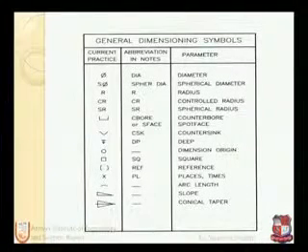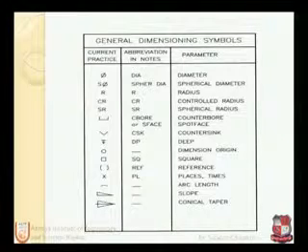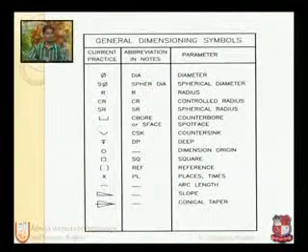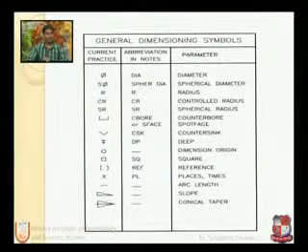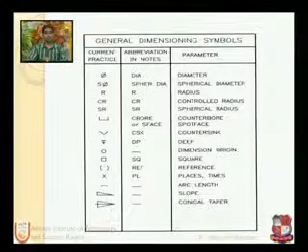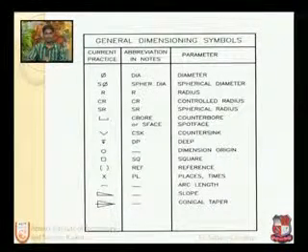So there are some certain special symbols. For example, the diameter is called phi, and it shows the full diameter of the circle. The next symbol is the sphere diameter, and to save space we write S and then the symbol of phi. This is called sphere dia.